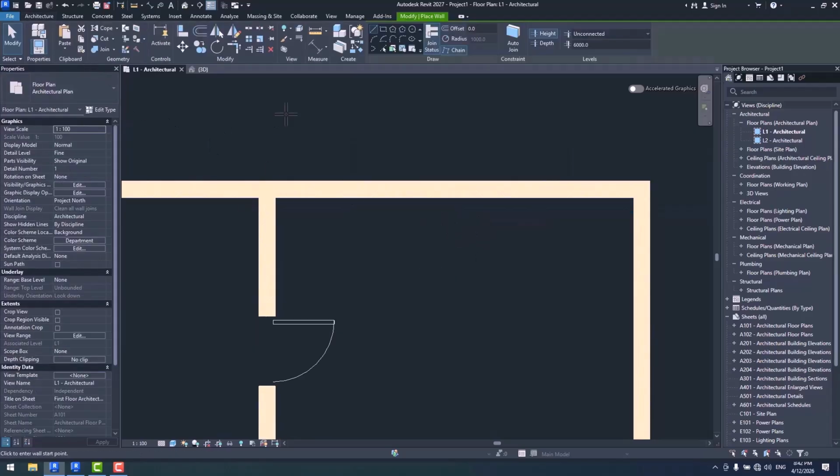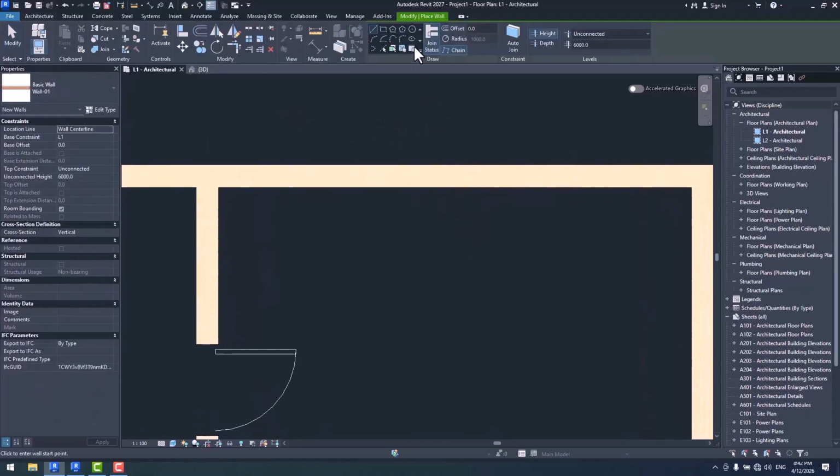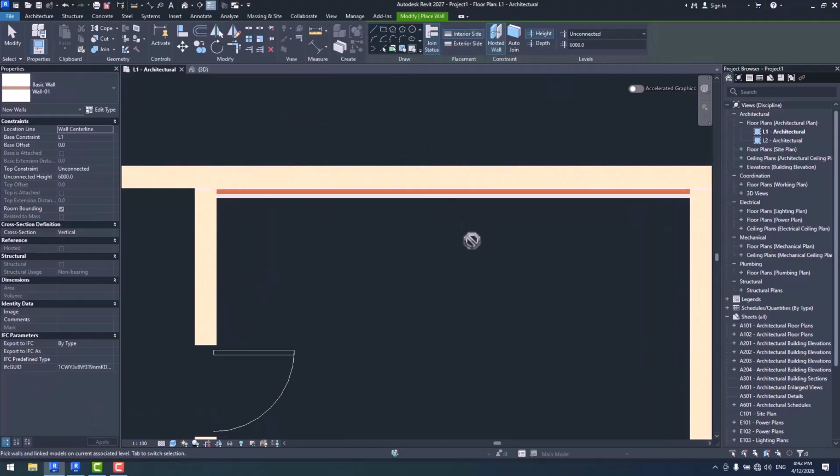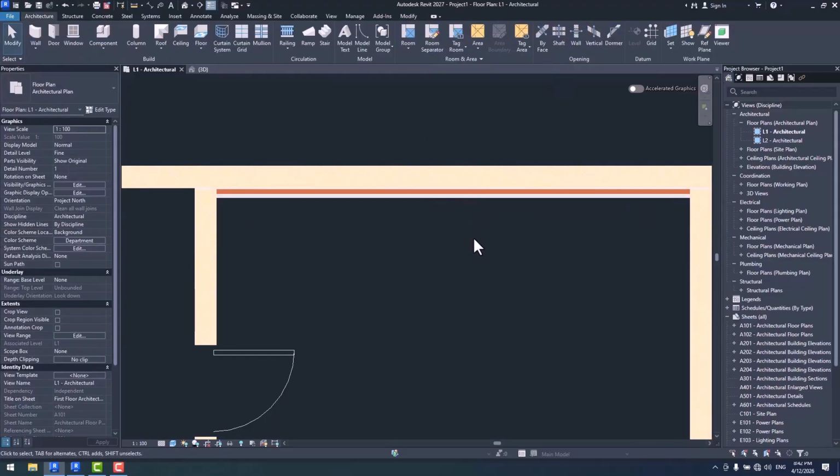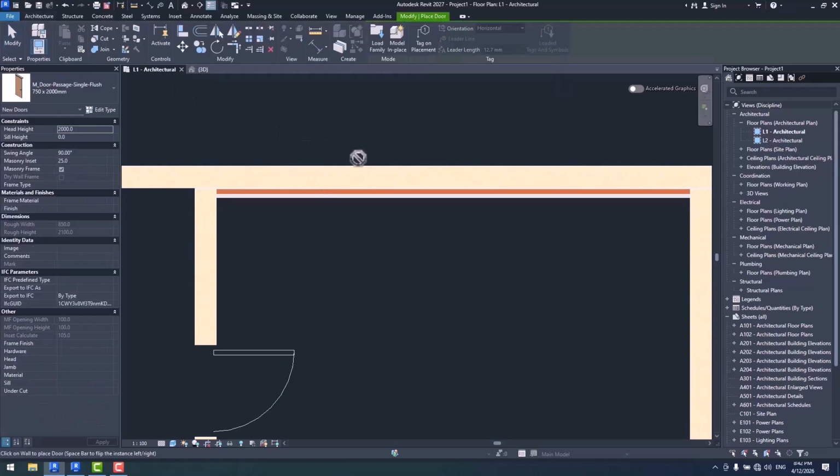Now let's talk about a point, guys. As you know, when setting the finishing layers or finishing walls separately, the next step would be joining them, right? I mean, we need to do this because we need to create the openings in the walls as well. Now, question is, when using place-based segment and hosted walls, are the walls joined up or not? Well, no, guys.